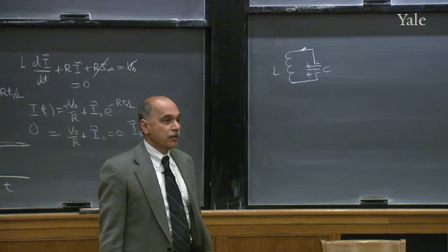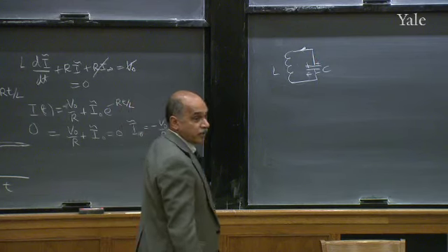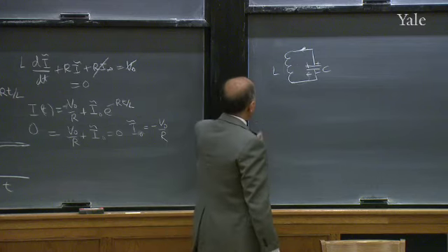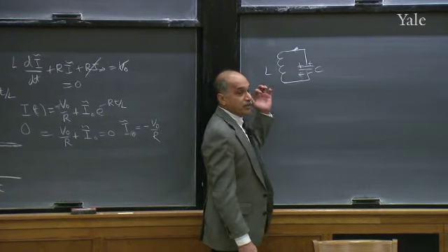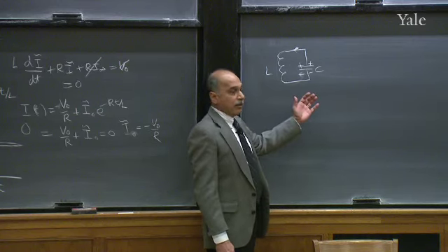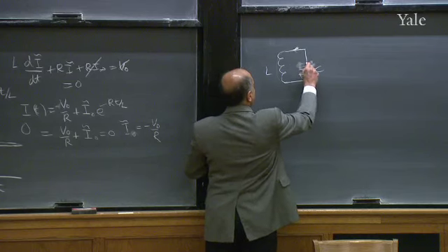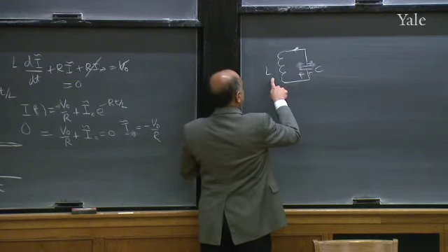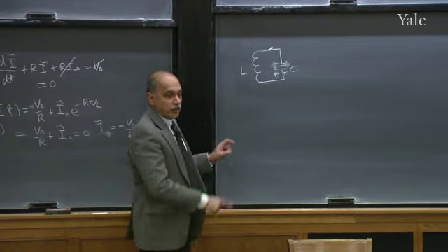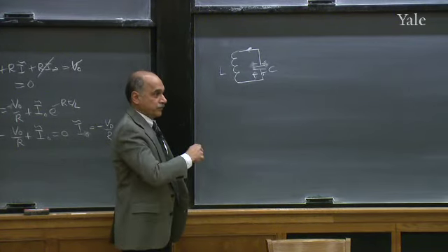Yep. Kind of like the inductor has momentum and it keeps pulling. The inductor would have had a current by then, so it is not going to suddenly stop having its current. It's going to keep driving more current for a while until the capacitor is charged up the opposite way to an extent that this fights that voltage, and then it'll go the other way. So it'll go back and forth.